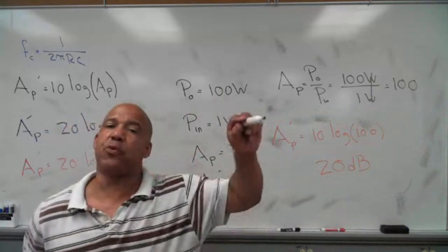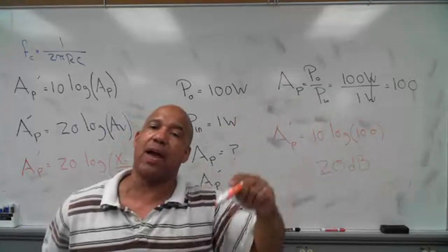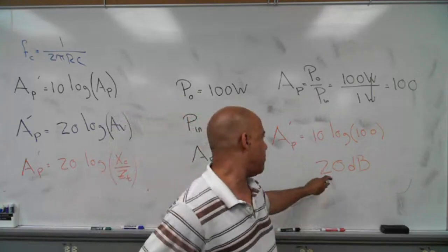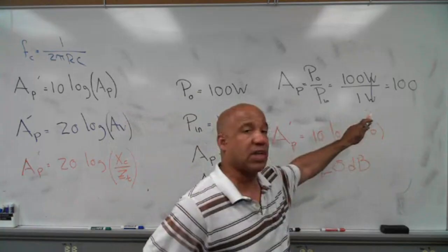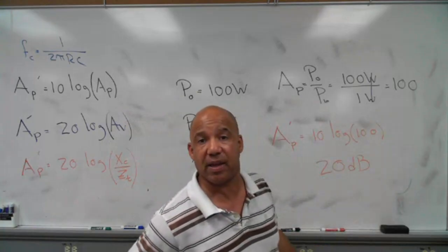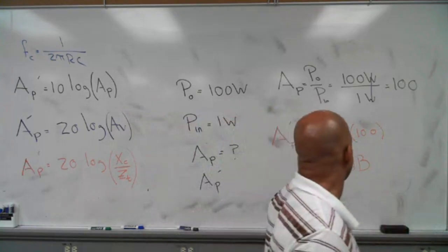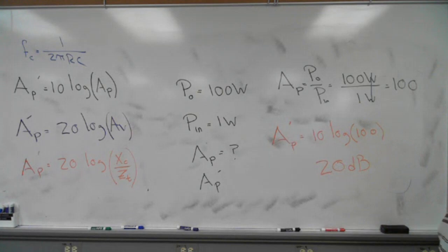Every time you go up 3 dB or down 3 dB, you either double the power or halve the power. So dBs are easy to work with. So if I go up 3 dB, whatever the power is, if it's 100, we'll go up to 200. There's a doubling for every 3 dB, or halving for every negative 3 dB. Does everybody see that? That's an easy problem to do. If I gave you that on a quiz, you can do that all night. Nothing hard about that one.